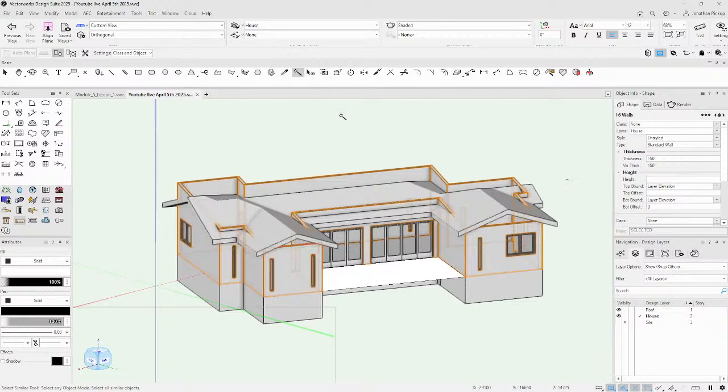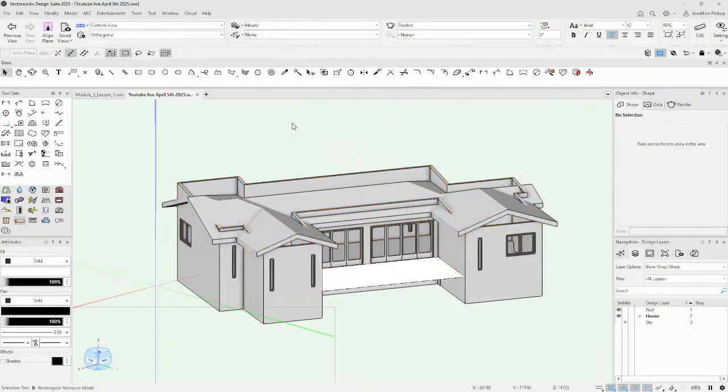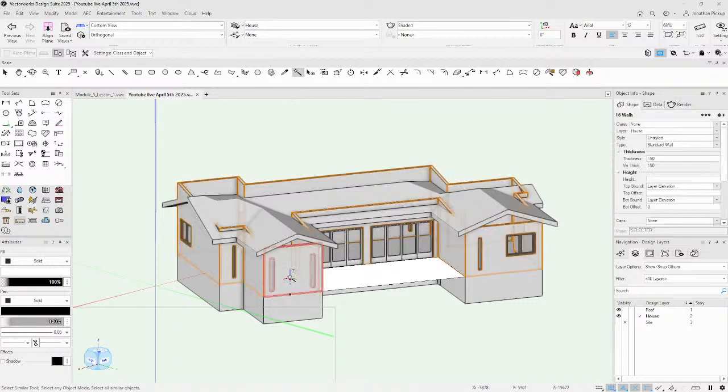Now that might be quite a handy thing to have on my, I've forgotten what it's called now, but this little selector that comes up, where you can select the different things. I've got the Reshape tool, Add Surface, Wall Join. So I've just added some of those to make it easy for me. But I'm going to go back to the Select Similar tool, select my wall, so it should select all my walls. Now the reason it's selecting just my walls is that I've already preset some of these settings.